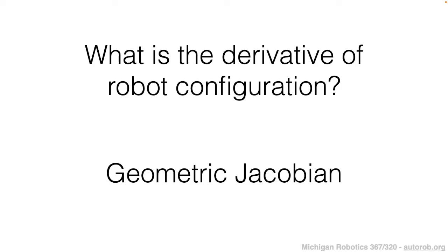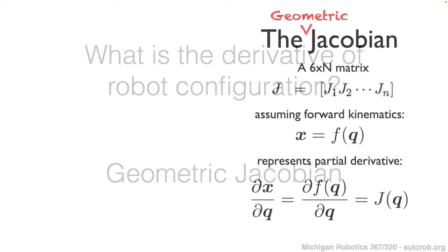So you'll recall from earlier in the lecture, we actually saw an example of the geometric Jacobian when we looked at the Jacobian transpose applied to 1 degree of freedom on our 3-link robotic arm structure. And so what we want to do now is extend the idea of a geometric Jacobian to handle all the degrees of freedom that exist within our robot, beyond just a single rotational joint. To do that extension, the Jacobian is going to extend from being a vector, which is what it was in that earlier example, to now being a matrix.